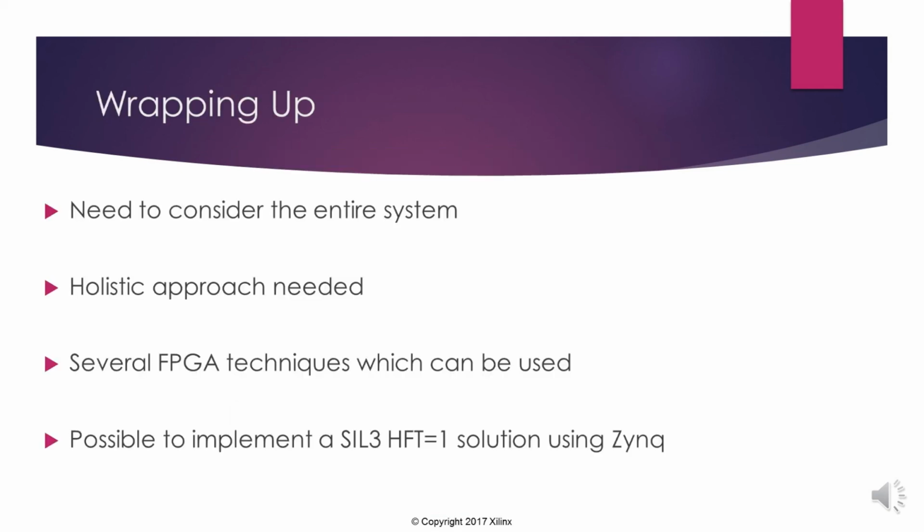So that brings me to the end of it now, and I'm going to wrap up. My key messages are, we really need to consider the entirety of the system. It's not just the FPGA. We need a holistic approach. We need to consider everything all the way down, and we need to consider the safety, the testability, and the security of it all from day one. There are several FPGA techniques that can be used to achieve this, and there are some examples in this slide pack. And an interesting message is that it's possible to implement a SIL 3 HFT solution using a Zynq, which to me is really exciting.